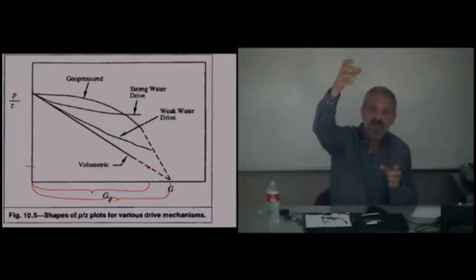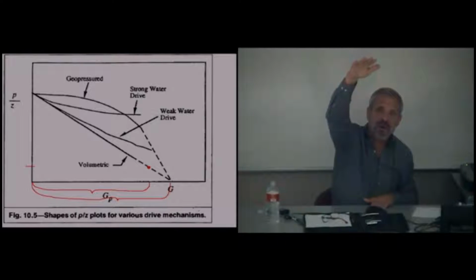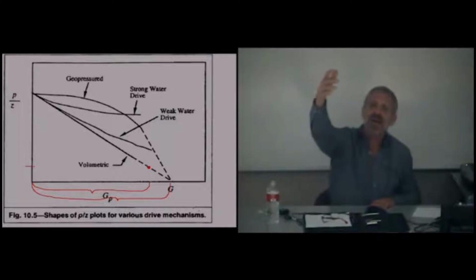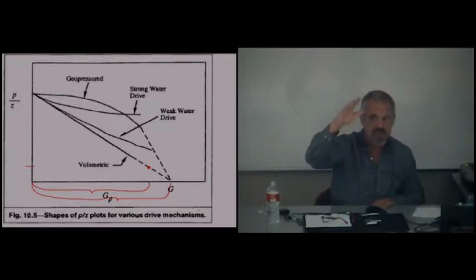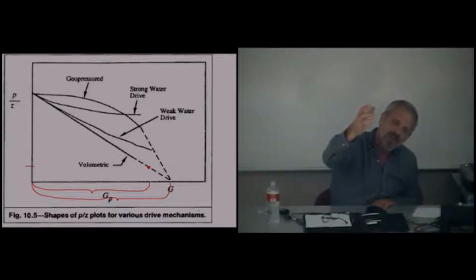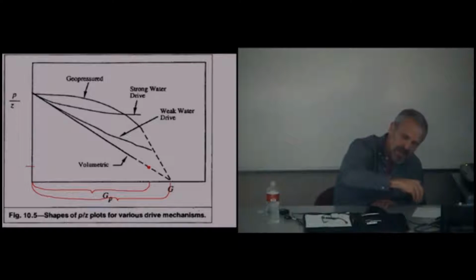It's a pretty low rate, and at 10 MCF a day there's some friction and some gravity loss. And then I'm also feeding a line which might even be 300 PSI, but let's say I'm feeding a low pressure line that's maybe 50 PSI. I can make a calculation in chapter 4, which we're skipping, so we'll embed a little bit of it tonight. There's some pressure and rate at the surface that will translate to a bottom hole flowing pressure.